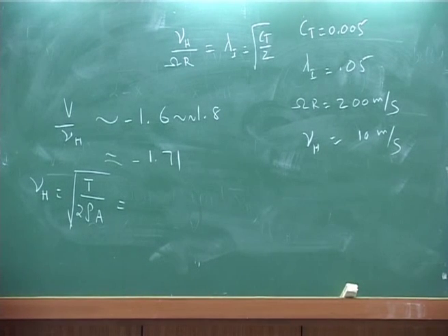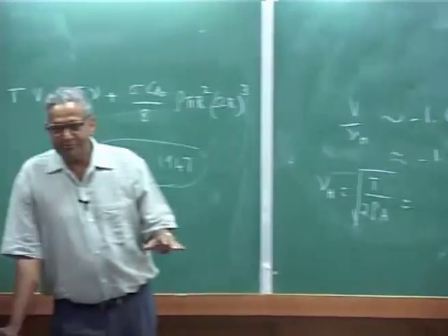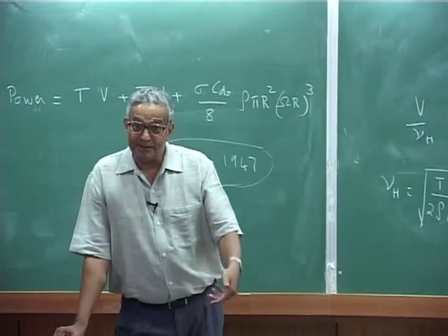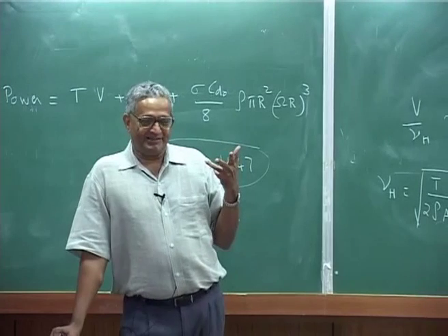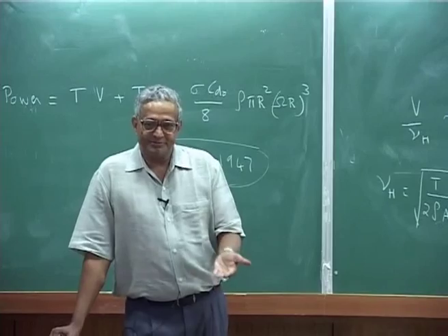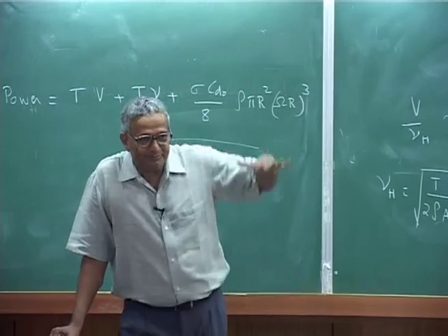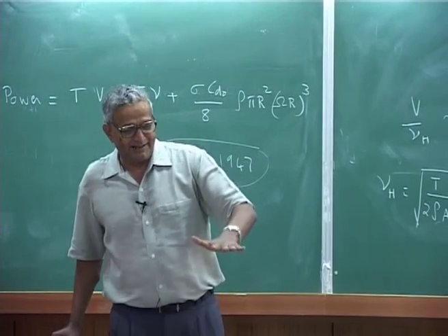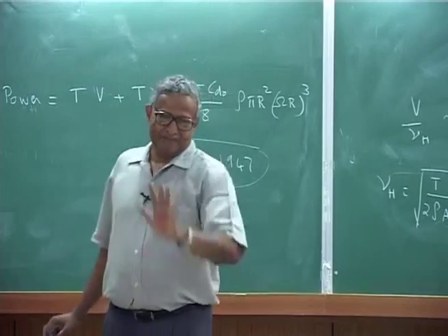But what pilot comes, he will not come and then hit 15 meter per second or 20 meter per second the ground. He will come near the ground, and then when he comes near, then he will try to climb up. Okay, that means he will increase his collective, and then he will try to, it is called flare up. So, he will come and then he will try to go up, and then he will slowly land.